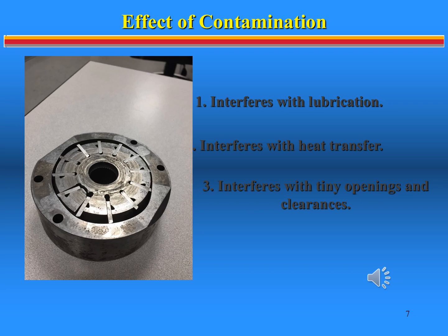Internal leakage or slippage, lowering the efficiency of pumps, motors, and cylinders, wasting power and increasing heat. Valves cannot control flow and pressure accurately. Corrosion, damage to delicate components, parts from fluid degradation, and sticking parts, causing erratic or intermittent component operation.